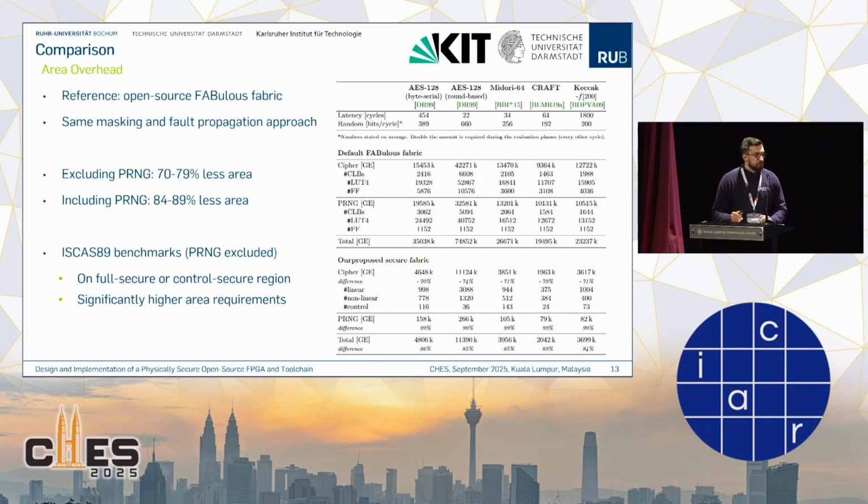Okay. If nobody has a question, I actually have a second question. You said the fault detector sits in the I/O blocks, right? Meaning that if a fault does not propagate until the I/O block, it would not be detected? Yes, exactly. That's why we ensure in every gadget type that it's actually going to be protected, or some faults that are injected inside a gadget might also be ineffective. So there should be no case where a valid dual rail state is set by an adversary by the fault injection.